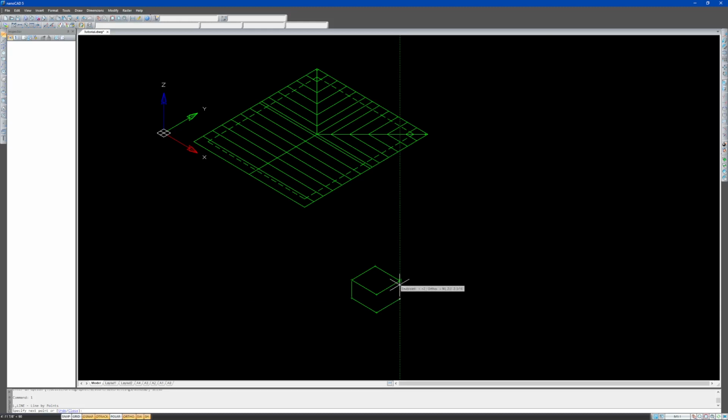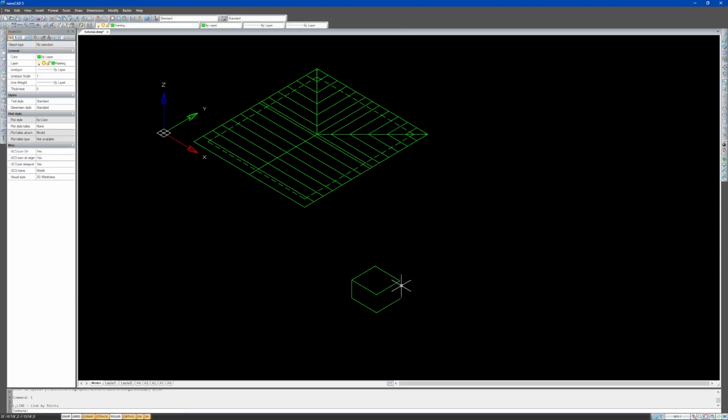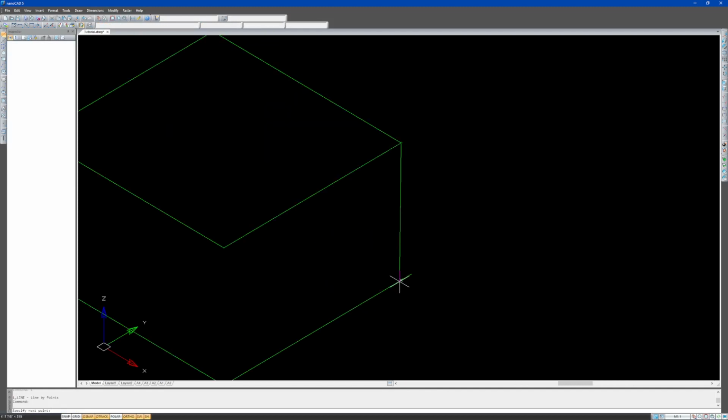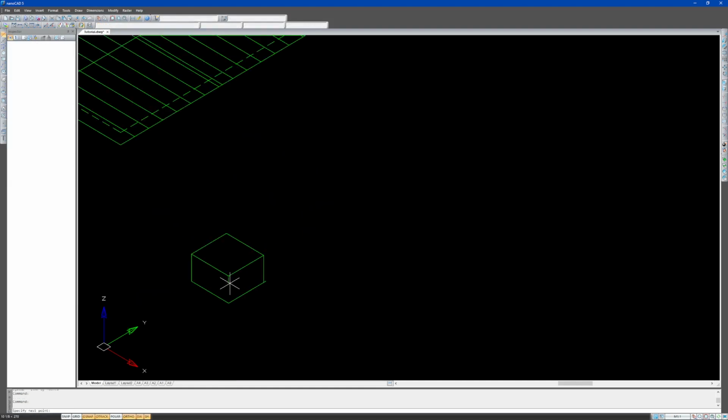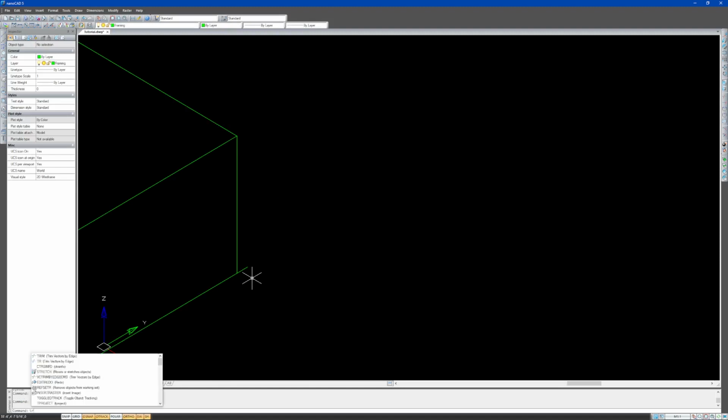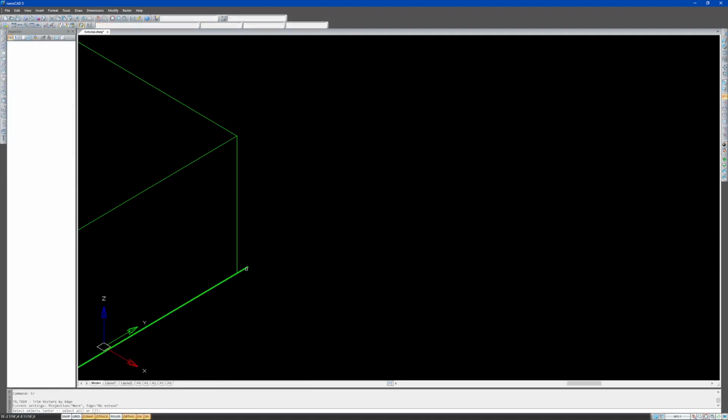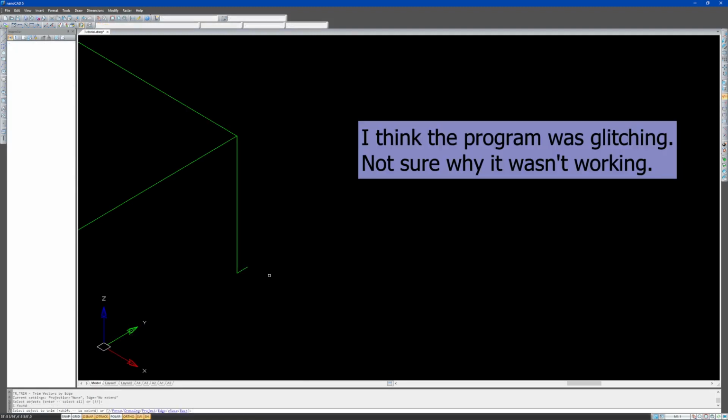By the way, I'm going to go over this as well, but what I'm doing here, how I'm tracking off of that endpoint, that tracking line, that is something called, oops, missed that one. I'm just going to start from here to here. There we go. That is called object tracking. And I'm just going to trim this last part, TR, enter, enter again. Oops.